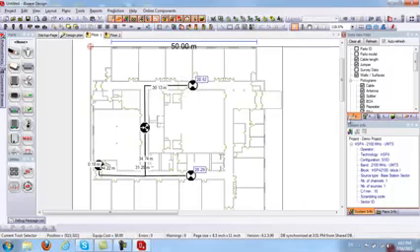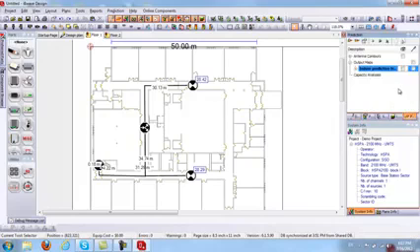So now I want to go ahead and create an output map and run predictions, but before I do that, I want to specify my prediction area. So to do that, you can draw a horizontal surface. So I will draw a horizontal surface. I can use this snap at the corner tool. I can basically draw a horizontal surface around my floor plan, basically to run my predictions indoor only, so that none of my signal leaks outside my floor plan.